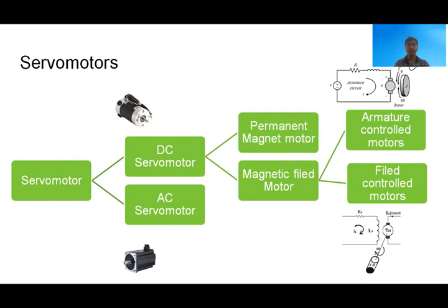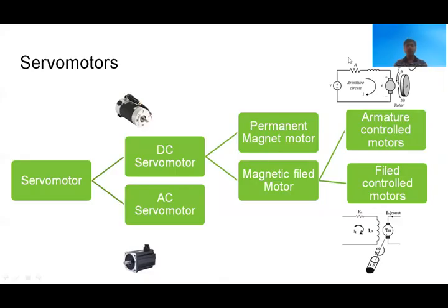Therefore AC servo motors are not suitable for high power position control applications. AC servo motors are basically used for low power control applications such as XY recorders, tape recorders, disk drive and printer applications. The DC motors are again classified into sliding contact motors with commutator brushes and brushless motors.